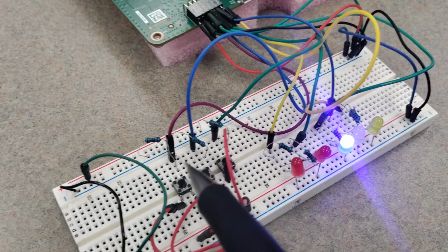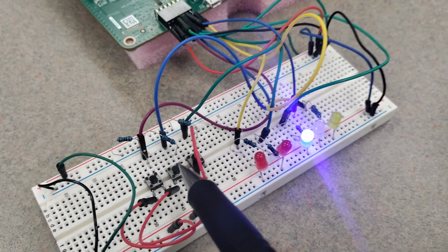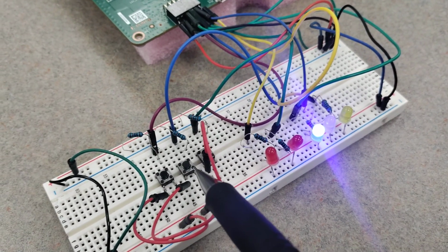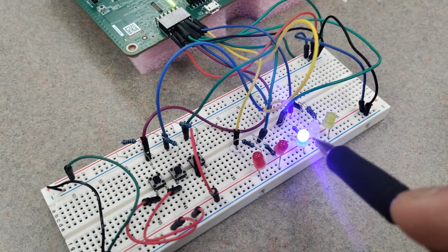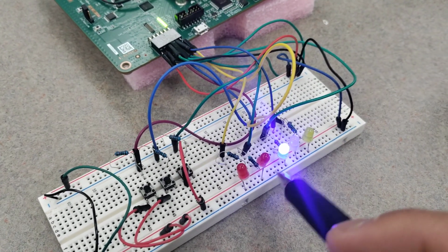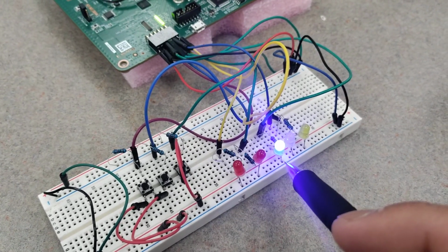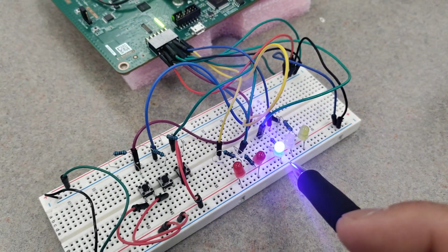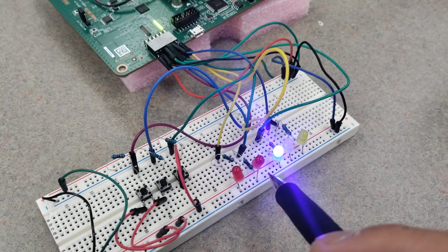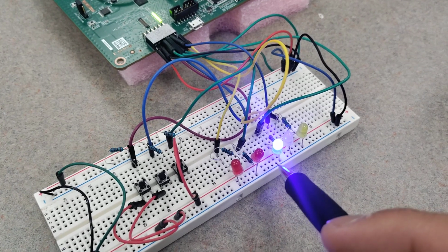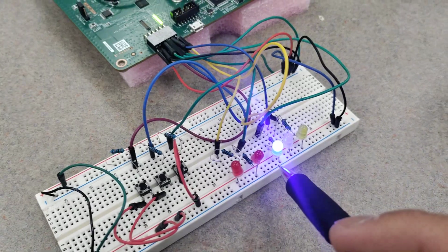So these resistors right here that are connected to the buttons are 10K ohm resistors. This is to ensure that we have optimal current flowing in. And for the LEDs, we have 220 ohm resistors. This is also to ensure that we have optimal current flowing in, so that the current isn't so high that it blows out the LED. Because with a diode, you have to ensure that optimal current is going in. Otherwise, if you feed too much current into the LEDs, we'll have to replace the LED as it is blown out.